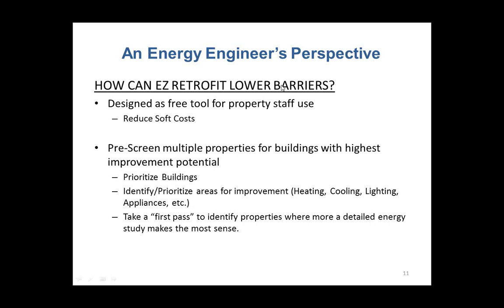Kenley alluded to this before. Most of the HVAC savings calculations are actually calibrated to the utility usage data that you input into the tool at the very beginning. Part of that is also weather normalization.